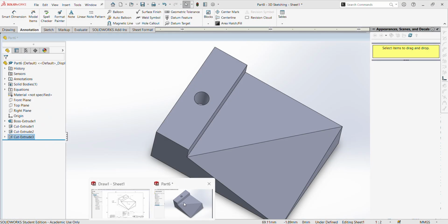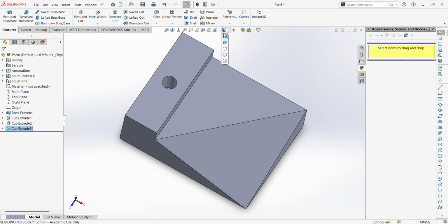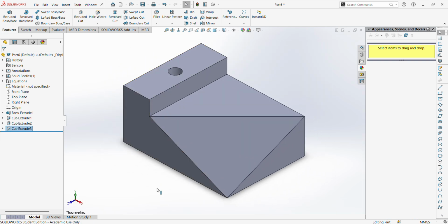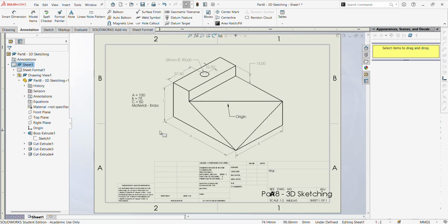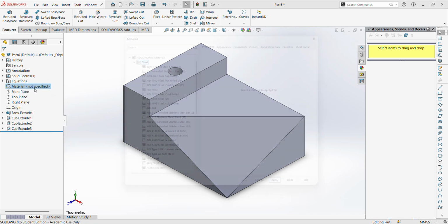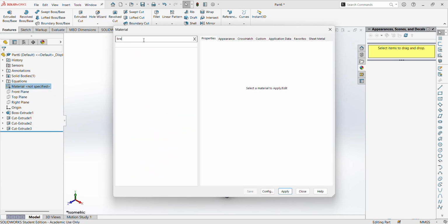Let's double check our ISO, and then let's double check our origin. And then, like we've talked about, we're going to put the mass properties in the description. I think the only thing we haven't done is changed our material to brass. Yeah, we haven't. Material brass there. But everything looks great. That looks great. Add material. And again, I don't like to skip through those. I like to type at the top. It's much faster.